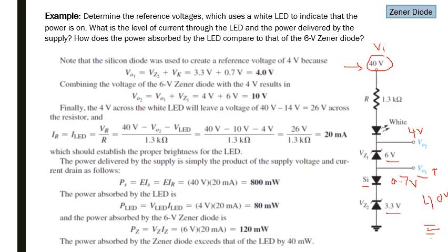And reference voltage 2, which is V02, should be 6 volt plus 4.0 volt, that is 10 volt. So V02 is V01 plus the Zener voltage of this diode, which is 6 volt. So 4 plus 6 is equal to 10 volt. So V02 is equal to 10 volt.